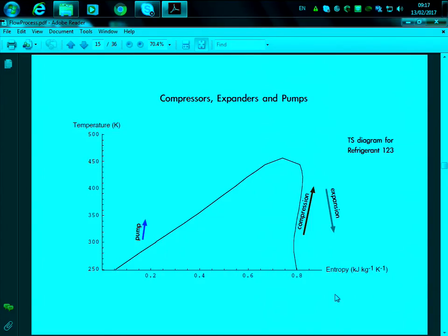But here we should also take into account the effect of the temperature. Not only am I compressing this fluid, I'm also increasing its temperature. So because of this effect, we have an overall increase in entropy, okay? But just keep in mind that this is the effect of the temperature, and in fact, if we were only compressing the gas, it would actually decrease in entropy. So whenever you first compress it and then cool it down, we increase the entropy and then decrease it somehow, okay? Can you see that process going through?